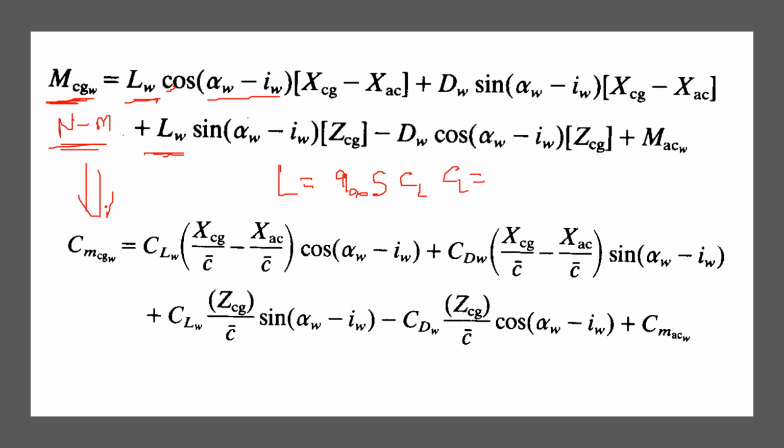You define CL as lift force divided by Q infinity times S. And the same goes for the moment. How do you define CM? Let's say your moment is M. So what you will do is Q infinity S, and you will take a length also here, because pressure into area is what? Force. So both dimensions are the same. This is a dimensionless number.